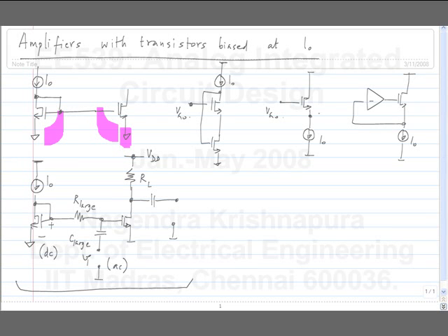How about the third one? Can we change this into a common source amplifier? This is in fact the easiest one, and this is also probably the most familiar. You want the signal to appear across the gate source. So incrementally, you ground the source for AC.